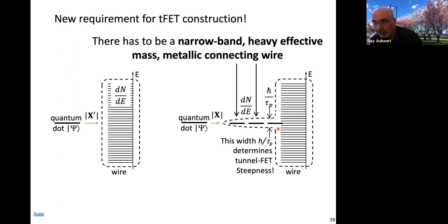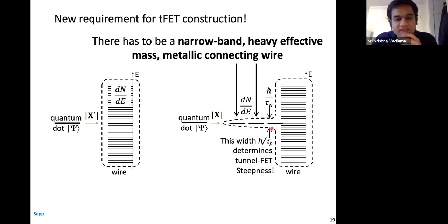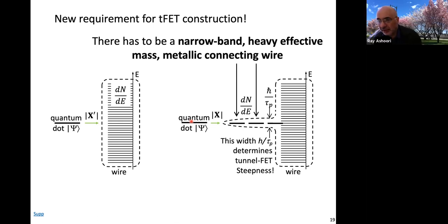I was wondering how Coulomb blockade affects what you see. Yes. So you'll get Coulomb blockade if the electron here doesn't very quickly go into the wire. If it stays here for long, then the levels get disturbed and you lose conductance. The limit for Coulomb blockade is also the quantum conductance. If you have a resistance from the dot to the channel that's greater than 25 kiloohms or whatever, then you expect to see Coulomb blockade.